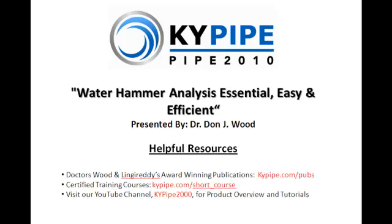I would be pretty uncomfortable not doing a surge analysis if I was using a surge anticipation valve. They certainly need to know how long it's going to take for the major negative or positive reflections to come back, because the timing is all based on getting the valve operating when the high pressure returns are expected to occur. So I would certainly want to see a surge analysis done at least by the people who are providing the valve.